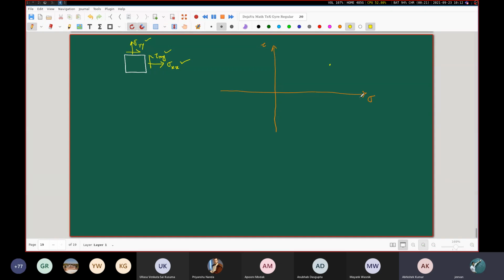But there is a problem in the sense that when you want to make a connection between the rotations on this sigma tau plane with the actual rotations that are taking place in this physical plane, because this is the geometrical sigma tau plane and this here is the actual physical plane. If we want to make a connection between the rotations in this plane and the rotations in this plane, there will be a mismatch if you take that tau up in this first quadrant. Okay, so a convention is followed which keeps things very neat and organized.